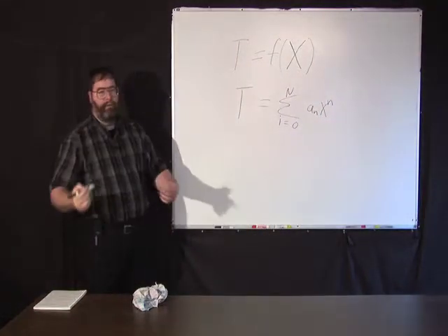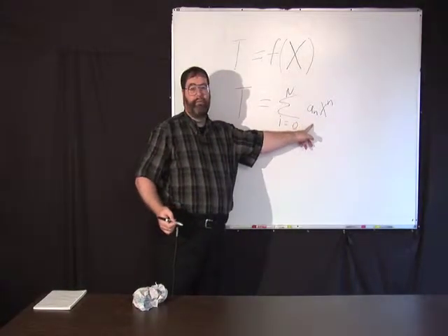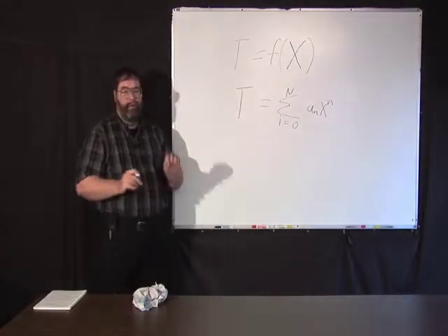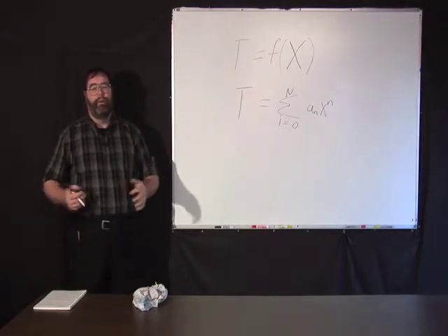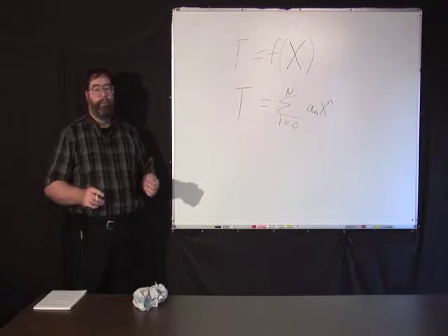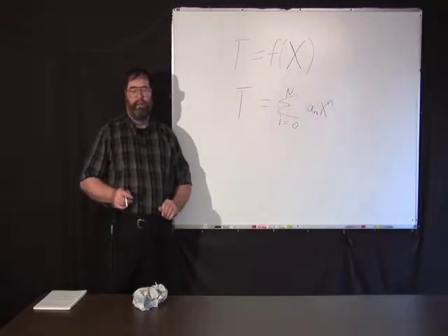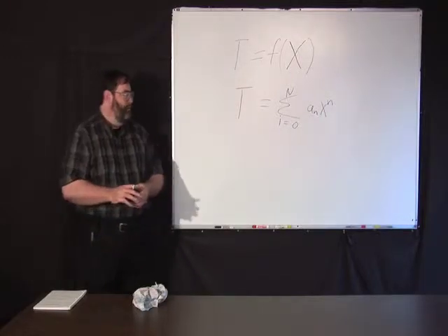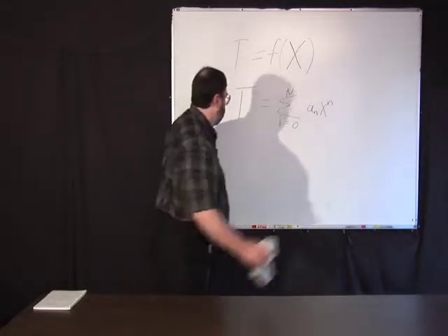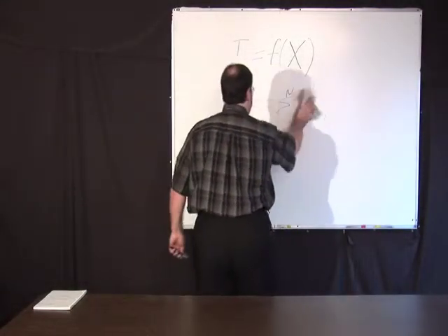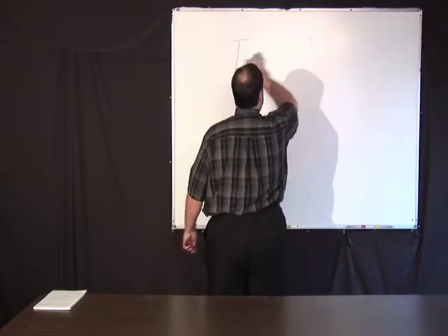So the act of calibrating the thermometer is determining what these constants are. And that's done by measuring this property at known fixed points and then doing some sort of least squares fit or some other type of fitting procedure to come up with constants to determine thermodynamic temperature with whatever you're using to interpolate temperature. Now, there are all kinds of things that you can use, and one of the things you can use is resistance.